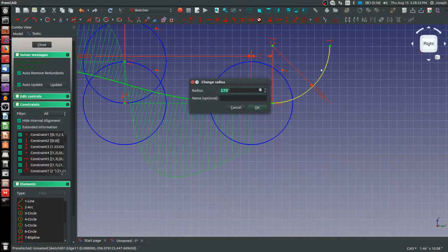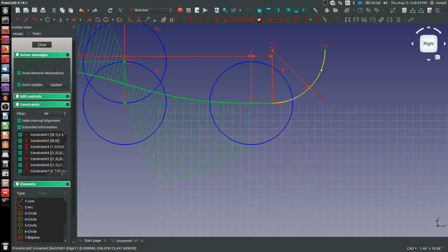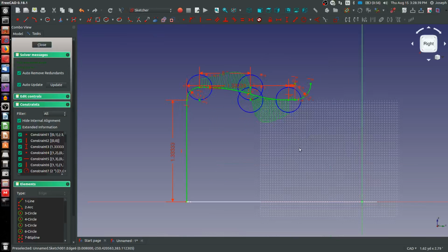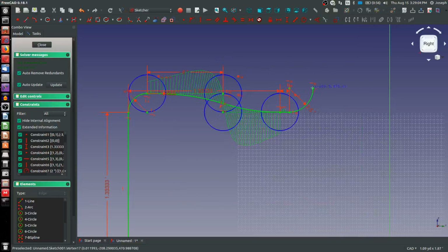Let's Shift R for radius and make this 2.5 inches. And there's a few things to consider here. I'm taking a big profile and sweeping it around here, and obviously I'm going to have a transform sketch here, here, maybe here, here, another one here. And as I extend the back of this chair really high, it's going to affect what I do down here already. So I'm going to have to break this up into probably 2 sweeps.